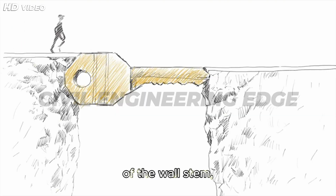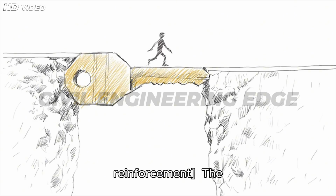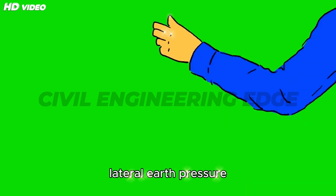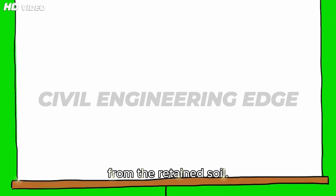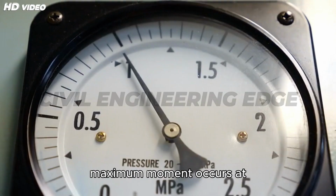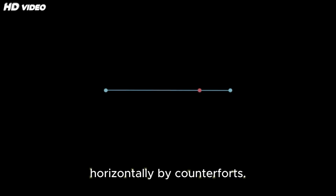Design of stem. Scene: cross-section of the wall stem, showing pressure diagram and reinforcement. The stem of a counterfort retaining wall resists lateral earth pressure from the retained soil. Since pressure increases linearly with depth, the maximum moment occurs at the base. The stem acts like a vertical slab supported horizontally by counterforts.